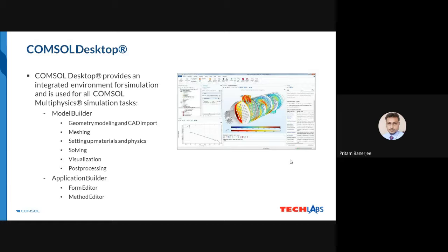With a fine mesh, it will take a lot of time to simulate, because all of those mesh elements have to be calculated, and it will also give you the accurate result. To get the accurate result, that many points have to be calculated, and for that the simulation time may increase.